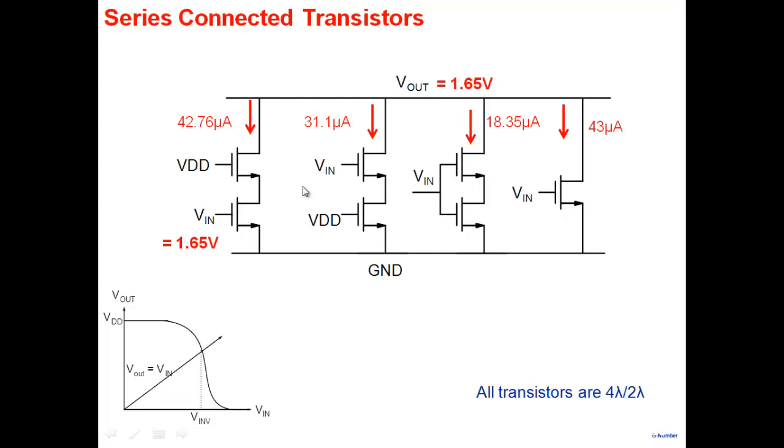All right. So look at these two NMOSs connected in series under different conditions. If you look at this case where you take two NMOSs and short them together, and you connect the voltage here. In this case, it can be shown that if you neglect, note that the other thing that is happening is body is connected to ground here. So threshold voltage of this transistor is a little bit higher as compared to this particular transistor. If somehow I could make the threshold voltage of this transistor same as threshold voltage of this transistor,